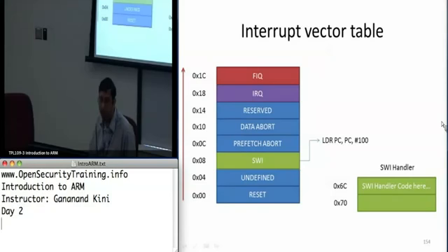But most of the modern processors like Cortex-M3, Cortex-A will actually have an instruction there which it will execute. So it sets the PC to 0 when a reset occurs and starts executing that instruction there. So if an IRQ were to occur, it looks up hex 18 address and runs whatever is there.